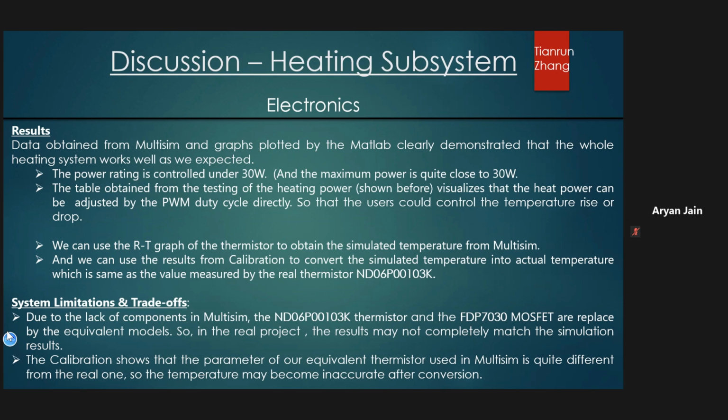The main problem is that the MOSFET and the thermistor used in the real world were substituted by the equivalent models in Multisim, which may lead to different results in the real project.